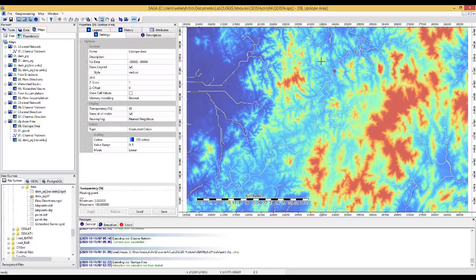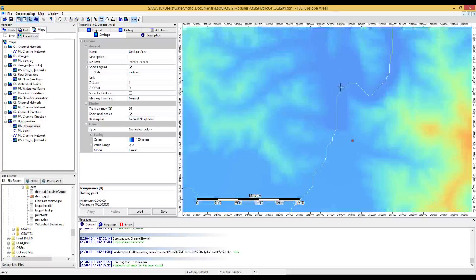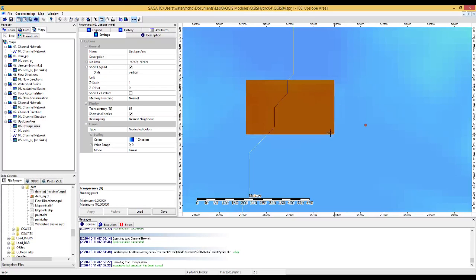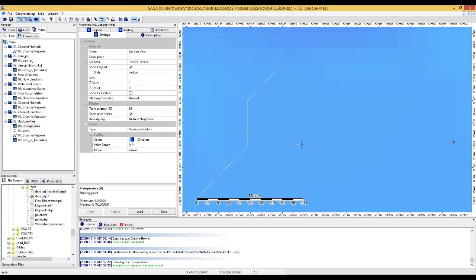After that, zoom in on this area to select the river with the endpoint of the river network. In that case, you should select this action button. Okay. After that, you can just assume the closest area of this river would be the outlet point. So just click.